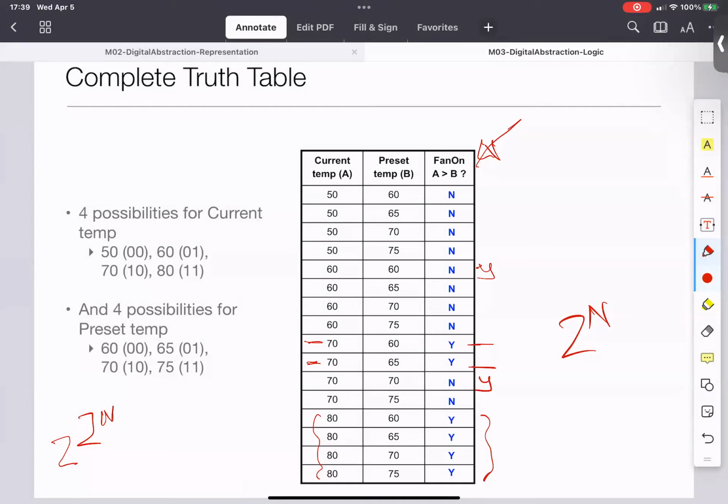So in particular, let's say n is 3. Then the truth table has 8 rows, and the final column can be filled in 2 to the power 8 different ways. That's 256, so there are 256 different functions there. Nothing terribly deep, but you should be comfortable with it.